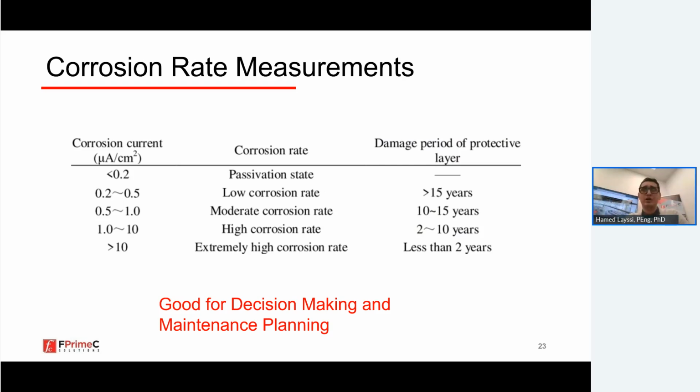And then once you run the test, which normally takes a few minutes to stabilize and get a meaningful reading with the commercially available devices in the market, this test is generally very slow, a few minutes for each test point. So we go very selective. We don't go on a very systematic grid like half-cell. If we wanted to do that with corrosion rate measurement, it would end up a very, very expensive test, and most owners don't wish to do it.